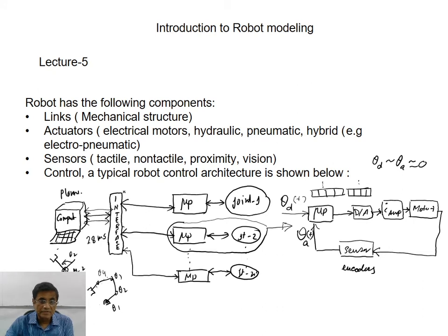So the interface keeps an eye on this actually. Every joint has an address, so it is monitoring which joint has already completed the task and which has not yet completed. Because unless all the commands in totality are executed here, there is no point of giving another set of commands, right? So the interface, like an orchestra controller, is actually doing this control job.